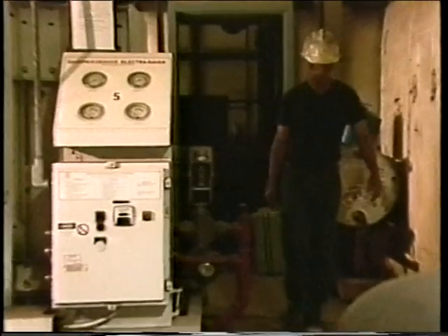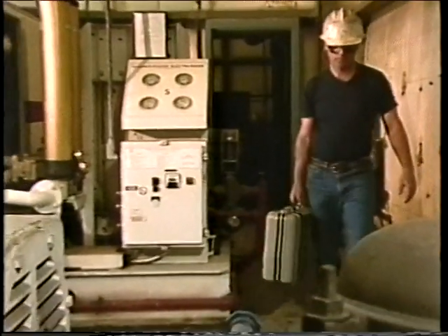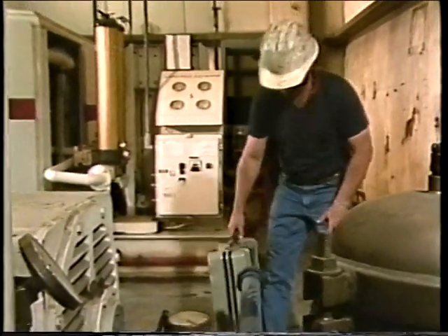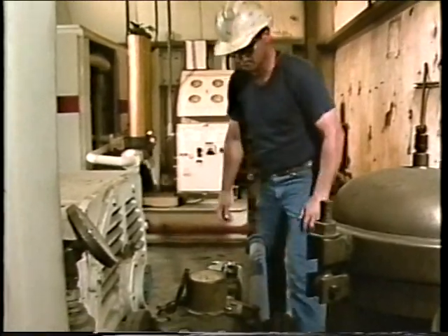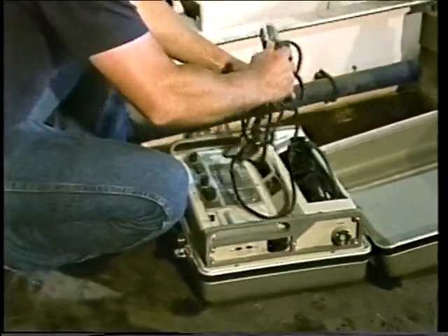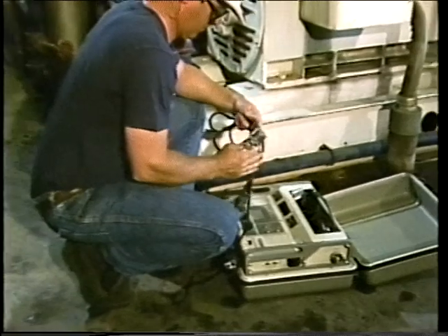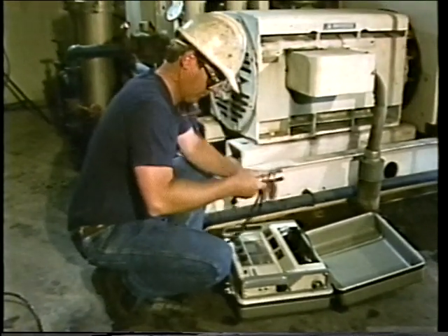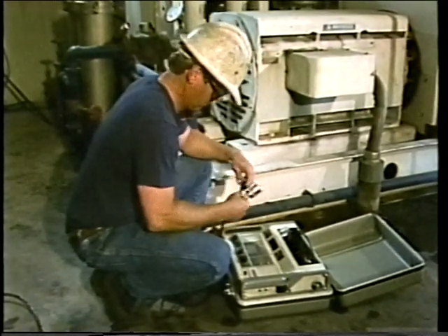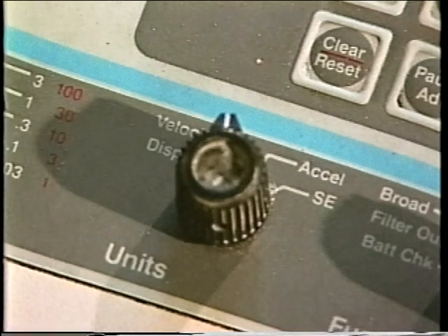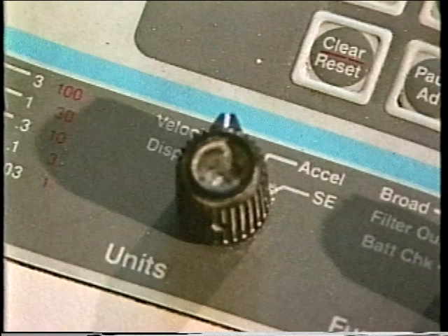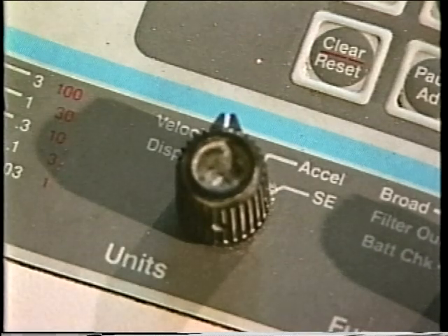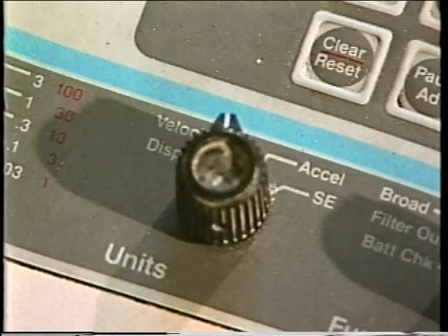All vibration analyzers have specific instructions that should be followed to ensure that the data collected is accurate. For example, certain preliminary steps should be completed before using the unit. First, it should be checked to make sure that it's in good shape. Once the unit has been checked, a parameter, either displacement, velocity, or acceleration, should be selected. This selection may be based on your company's vibration monitoring program or on the speed of the machine being monitored.